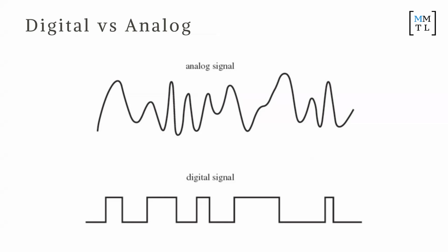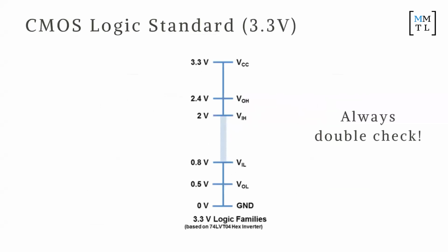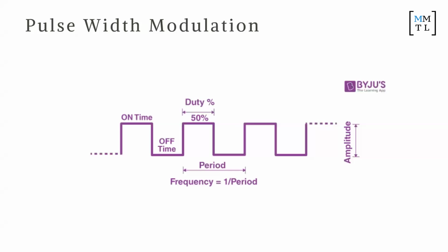Yes, exactly. So you have an equal time spent in 0 and equal time spent in 5, and it will average out to 2.5. Okay, so this is a strategy that is very popular and very common everywhere called pulse width modulation, or PWM. Basically it says that you can get an average value of any value you like between 5 and 0, as long as you duty cycle it for some time. So if you turn on 5 volts for 50% of the time and 0 volts for 50% of the time, then it averages out to 2.5 volts. Does that make sense?